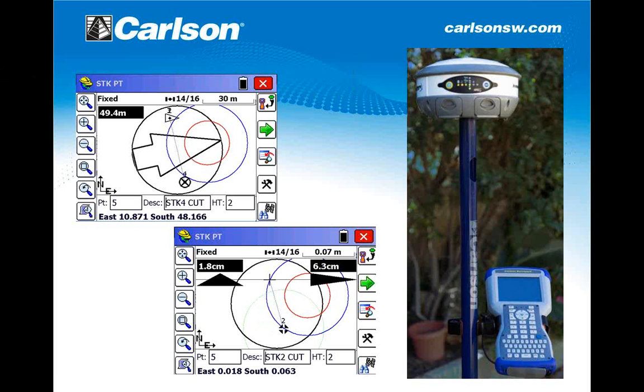receivers with a full set of sensors, IMU sensors, I would talk about tilted pole measurement. Okay. We are working on tilted pole. We have done some implementation. We have started to experiment with this on the Stone XS10, and I tell you that is a really nice feature. Okay, we are refining.